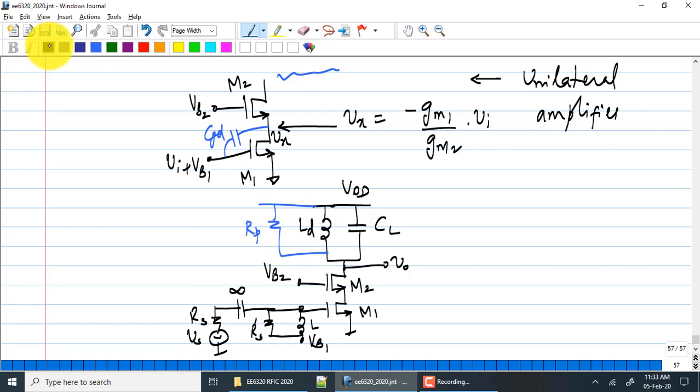So the gain of the circuit remains the same as before. It does not change. Okay. What is the noise figure of this circuit? Well, actually, wait. The gain does change slightly. Now that you have added a cascode, it is no longer RDS, it's Rout, which is hopefully much larger than RDS. So now we will just approximate it to RP.